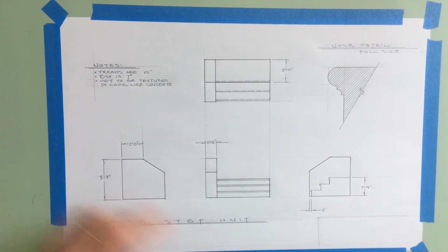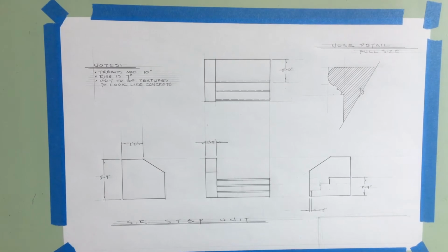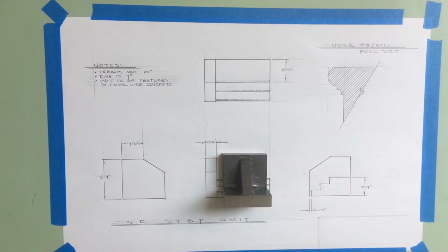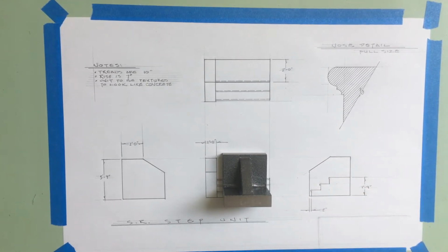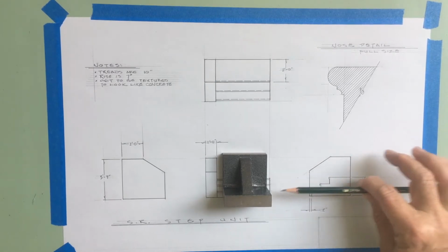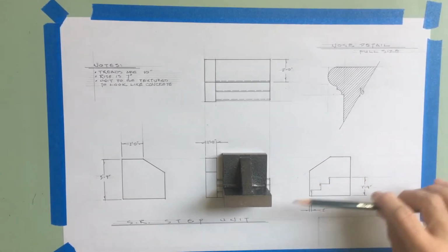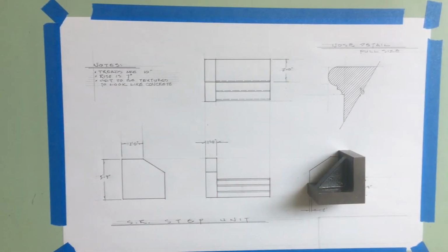And here's an interesting thing that I want you guys to understand. We're going to use our little model makers block again. If that is the front view, a view drawn over here is a view looking from this direction. In other words, if the view is drawn here, it's as if you're standing here and looking that direction. And if you're standing here and looking that direction, the front will be on your left, so that's what that side view looks like.